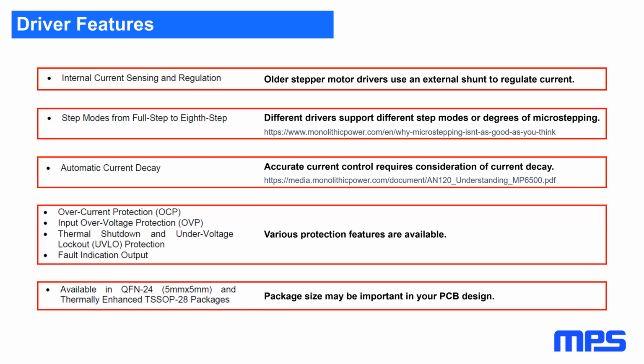Protection features are necessary in stepper motor driver ICs. Overcurrent, overtemperature, under and overvoltage protection can save the IC in the event of a short circuit or a power supply problem. Fault indication is useful to allow your system to recognize that there's a problem.